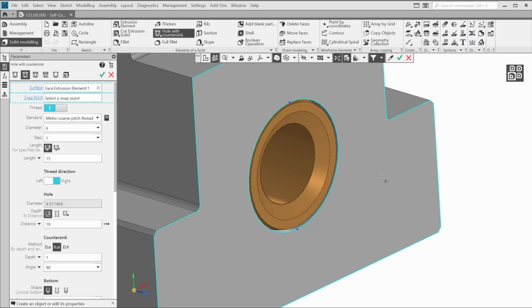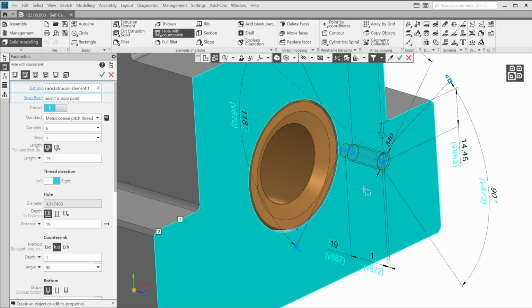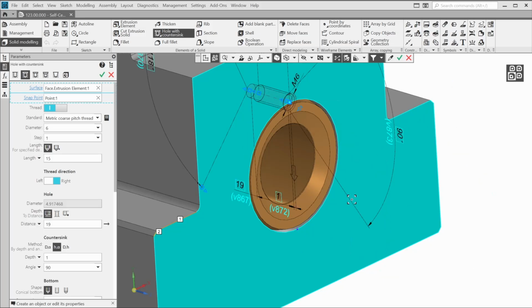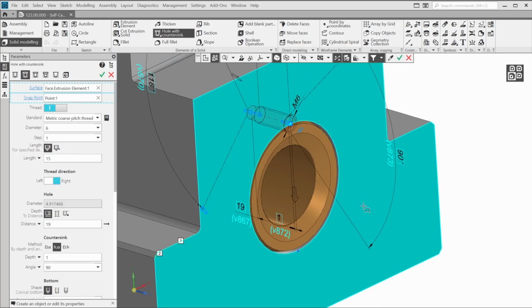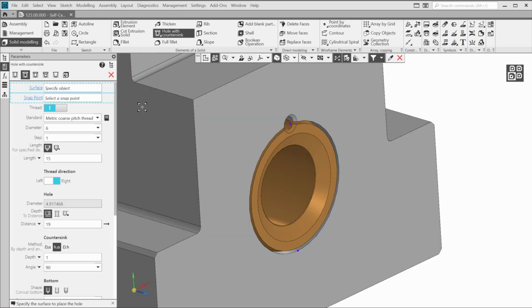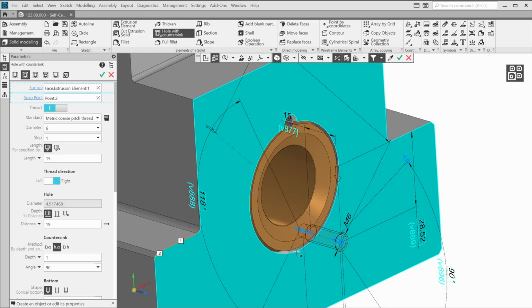Select the flat face of the moving jaw and select the upper point. Follow the snap symbol to ensure you're selecting the correct object. Notice that you could select the point first and then the surface. As you saw, both fields were active. Confirm. Don't stop the command and create the second point with the same parameters. As you can see, all the adjusted parameters remain unchanged because we haven't stopped the command. Select the face and the lower point.